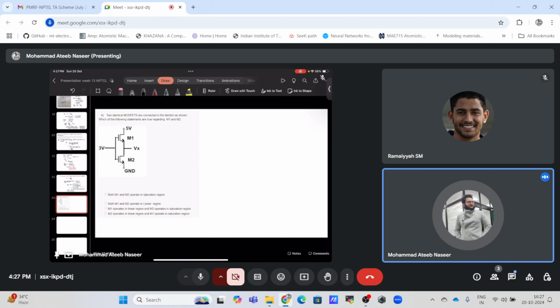So the more precise statement is that in the early stages of the non-saturation region, the MOSFET will behave as a resistor, let's say for a few millivolts. You must have heard of the sub-threshold region. In that region the MOSFET will have resistive behavior. It's not always true that the characteristics will be linear in the sub-threshold region as well. I'm talking about novel devices.